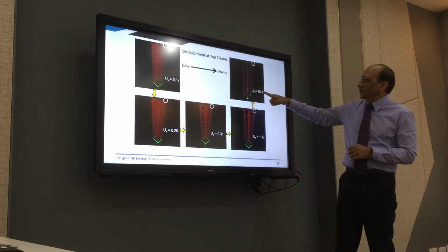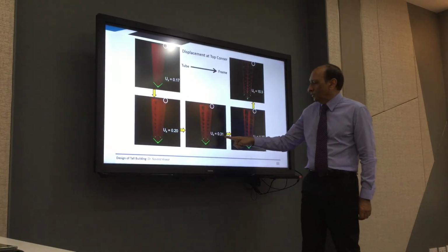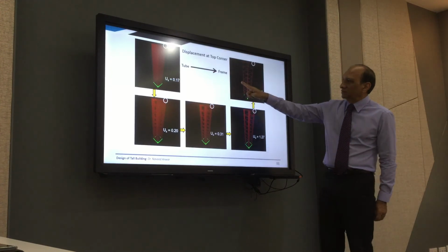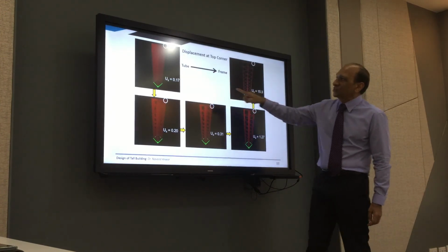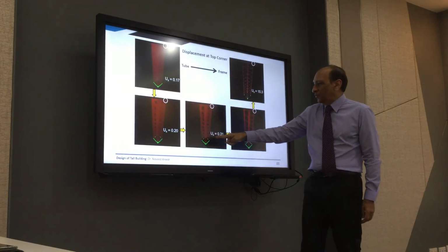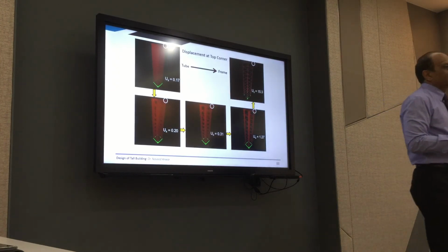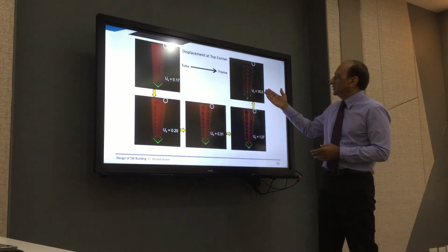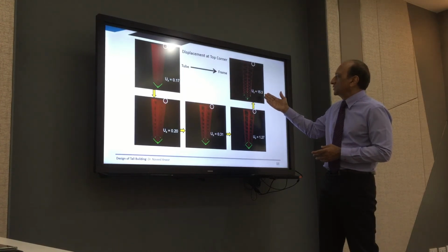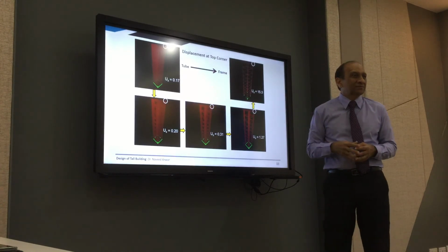So you can see displacement 15, 0.7, 0.2, 0.13. Pure frame, displacement is very large; pure wall, very small; in between it varies depending upon the outrigger effect, right? So you can say that the stiffness of this frame is about 45 or 50 times smaller than that one.